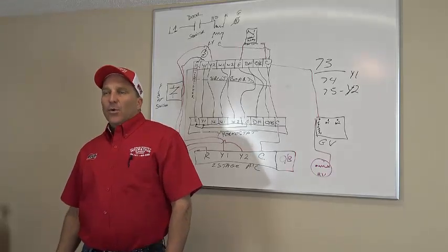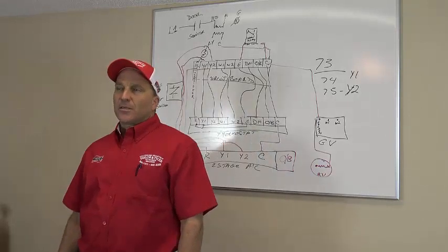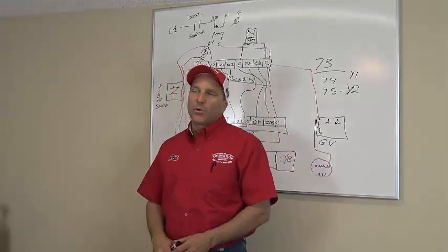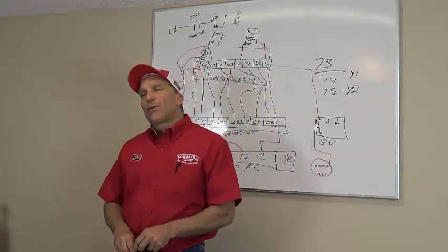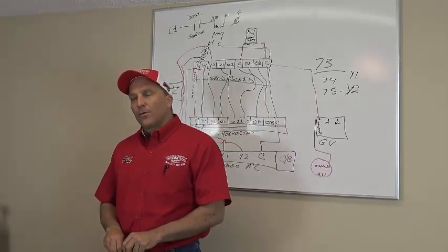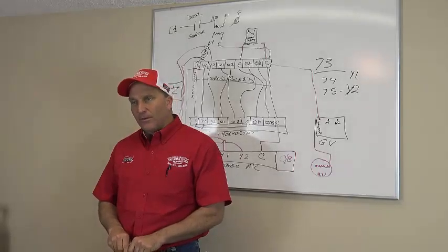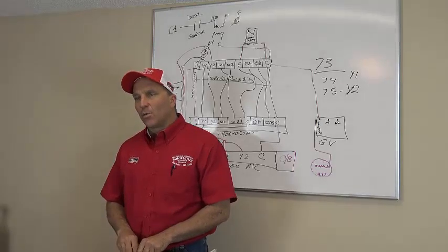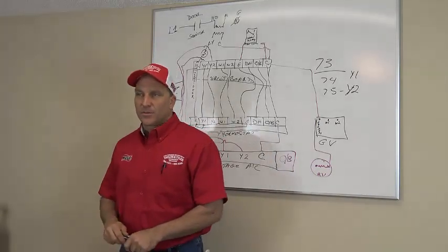If you've got a zoning system and you put the EWC zoning system on the 50-50 rule, the 50-50 rule will not allow second stage to kick in unless over 50% of the zones are being called for. So if you have 3 zones and 1 is being called for and the 50-50 rule is energized, Y2 will never be energized because only Y1 will be, because you are not over 50% of the zones.